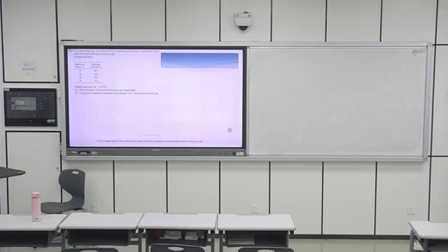Draw the flow curve. The x-axis is number of blows, the y-axis is water content. You've got two columns of numbers in here, just draw the plot. But the x-axis is in a log scale, keep in mind.